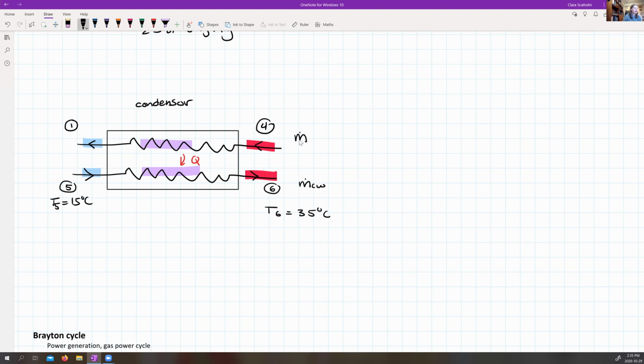And if you remember what I said last week, we know that there's steady state, so dE over dt is equal to 0. There is no Q, and I know this is often confusing. There is obviously a Q, right? But it's because of what I'm considering as a system. There's a heat exchange between the fluids, but my system is limited to this. Here, there's no heat exchange with the environment, okay? So that's why my Q is equal to 0. Minus my work equal to 0, I'm not pushing or stirring or anything like that. Plus my flows, that's the important thing. So my sum of flows in minus my sum of flows out, exits. So this is the important bit.